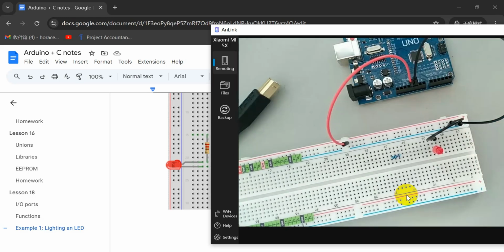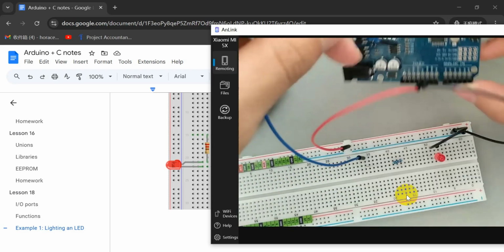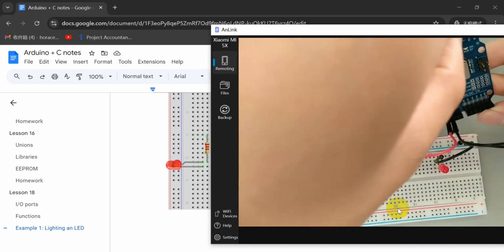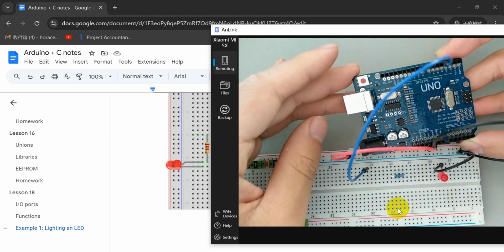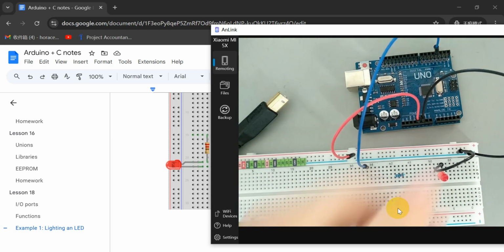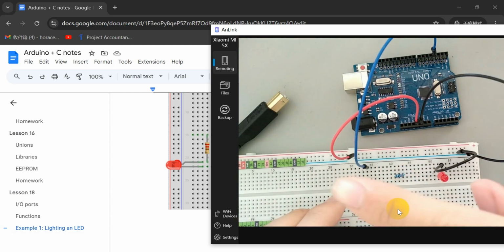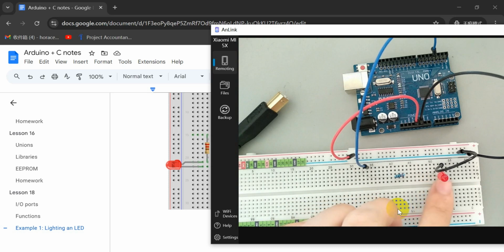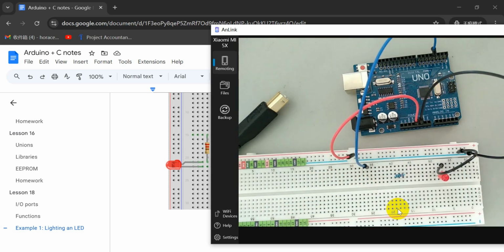And then we can connect this end to PWM port digital 3. So it would be this one right here. 0, 1, 2, 3 here. Like so. Alright. Now the hardware is done. As you can see, it comes out through here and then goes through the resistor, through the LED, into this, which brings it to the ground. We didn't really need the 5 volts for this, but it's alright.